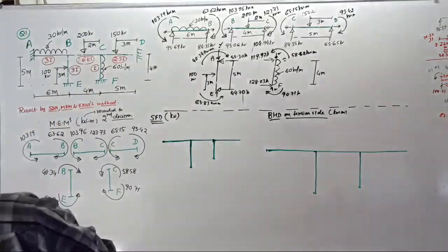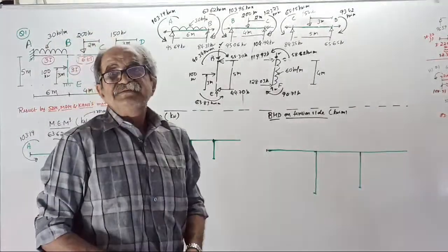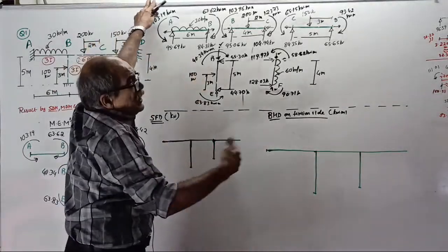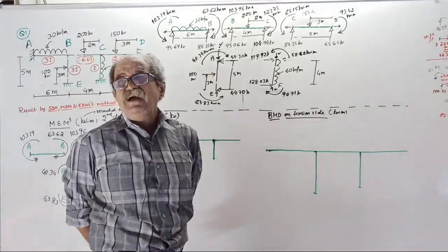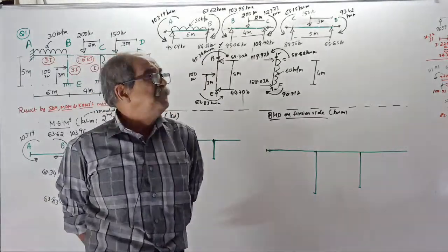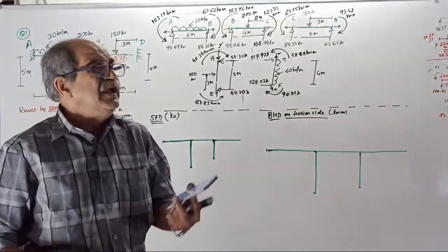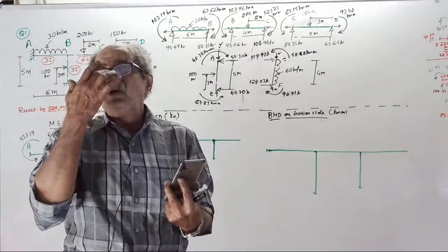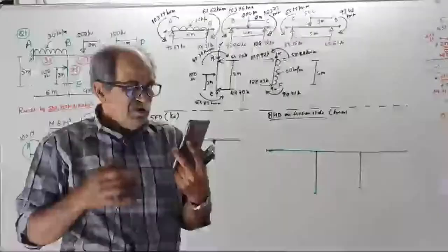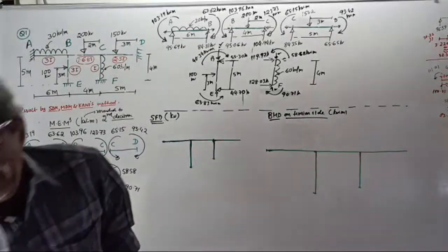Okay, start. Now see, shearing force diagram, all in kilonewton. Sign for the beam will be left up, right down, positive you can take. For column, it is your choice. First of all, remember, for shearing force diagram, important, how is the diagram? But when you design, do you require plus minus sign for shear force? Tell me. In RCC or steel, do you require plus minus sign for shear force? When you design RCC or steel, no. Therefore, sign, I will put some sign here.